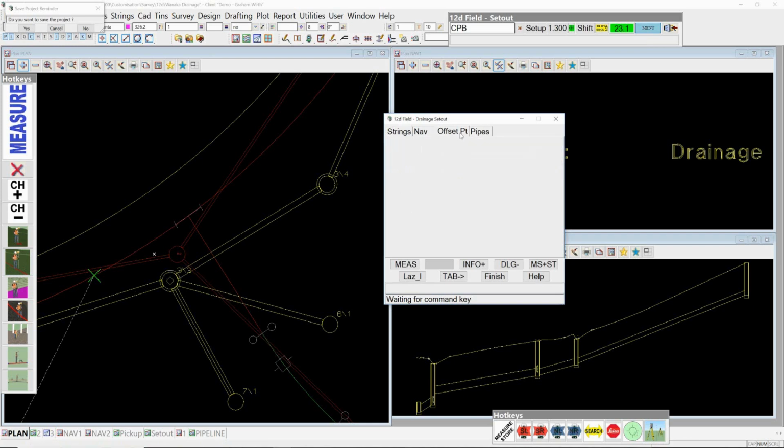And if I go back to offsets, I can now put that as 2 metres to the right, so we can line up 2 pegs, and you can also go forward along the line of that perpendicular to the change, or back from that as well. Now you're not required to set that direction relative to the alignment. You can type in your own individual item within that as well. So that's a little overview of the drainage setout.